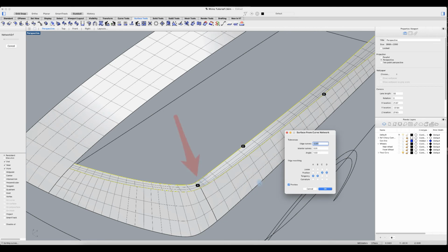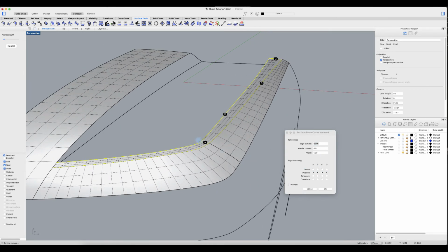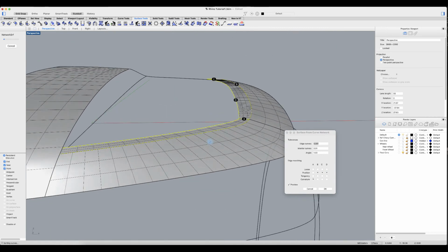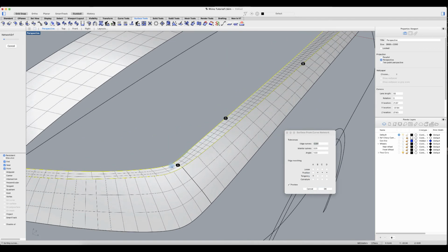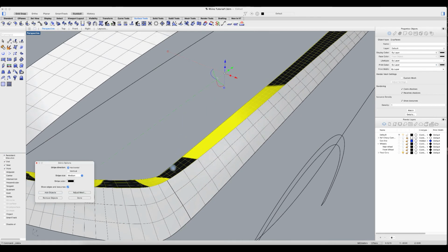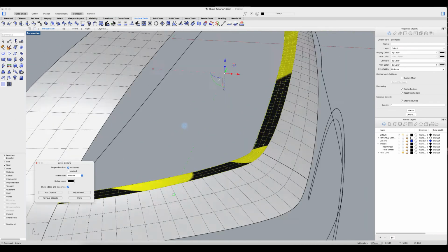And so you see there's a little warble right there, so let's go back to position. Got everything to position. I always like beginning with placing it in position, and I want to push that on A. I want that to come up so I can see if I go with curvature, it actually creates those bumps, but if I do tangency, it's absolutely good. So I'm going to work with a tangency there, which is absolutely okay. And let's turn on our analysis right there, and you can see my zebra analysis much better.